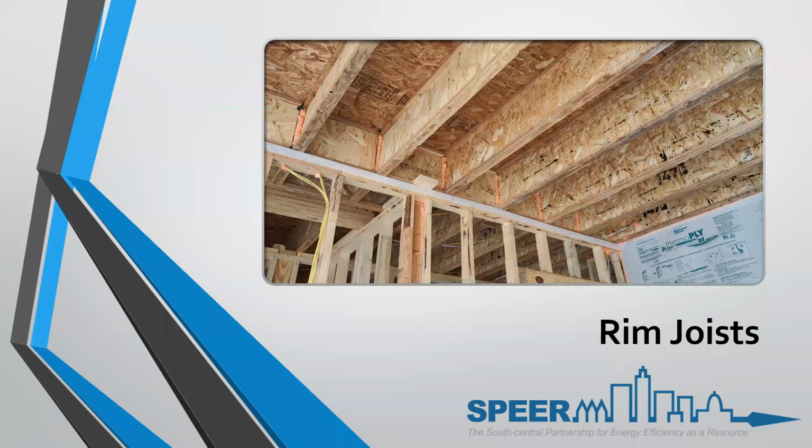So rim joists are not only at the perimeter of the building. A lot of times when we look at it from some people's perspective, you see the rim joists as just, as we always called it, the belt around the house. But when you've got different levels of homes, like a second floor or third floor, and those are different than the first floor footprint, you now must also create rim joists or band joists around the perimeter of the conditioned floor below the second floor, below the conditioned floor above.